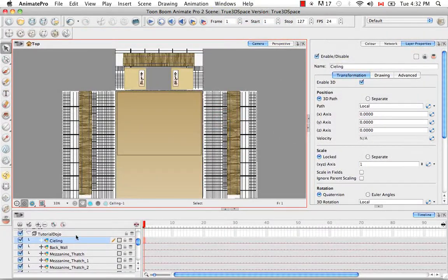So the moment that you change these layers to 3D, enabling the 3D, you're allowing these tools to also become 3D when that layer is selected. So the 4 tools that I mentioned are actually the Translate tool, the Rotation tool, the Scale tool, and the Transform tool down here. When we're doing positioning, be sure that the Animate mode is off so that all the movements you make are not being recorded as keyframes, as movements that you want to see animated.